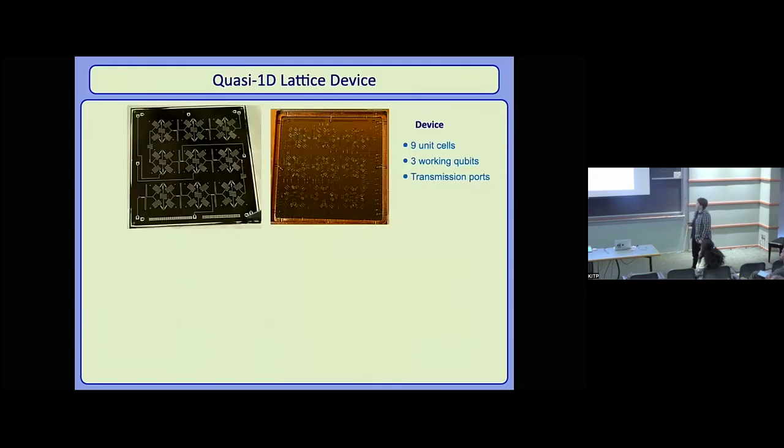So in practice, this is what it looks like. This is a photograph of the chip at the photolithography stage. What you're looking at here is a tantalum film. That's the black that you can see. And everywhere that's white, you are seeing through sometimes about a 10 micron gap in the tantalum film to a white tech white behind. Once you actually package it up, it looks a lot messier. This is now entirely wire bonds that you're looking at. Anybody that has worked with a wire bonder knows the amount of patience involved with sitting and doing this many of them. But we've cooled this down during March meeting in proud superconducting circuits tradition.